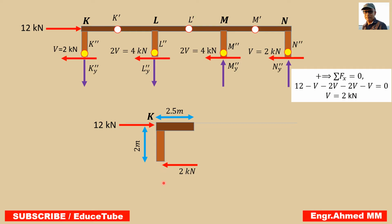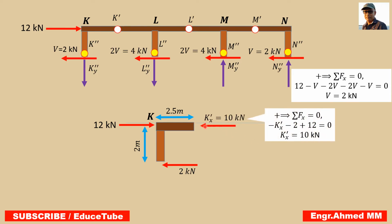Now we can go for the vertical component, but before that we can find this very easily, because if we take summation of horizontal forces equal to 0, easily we can find this horizontal reaction component, that is K'x. Because I took the right direction as positive, the left direction will be negative. So minus K'x minus 2 plus 12 equal to 0, because this is plus. So K'x equals 10. So summing horizontal forces, we found this.